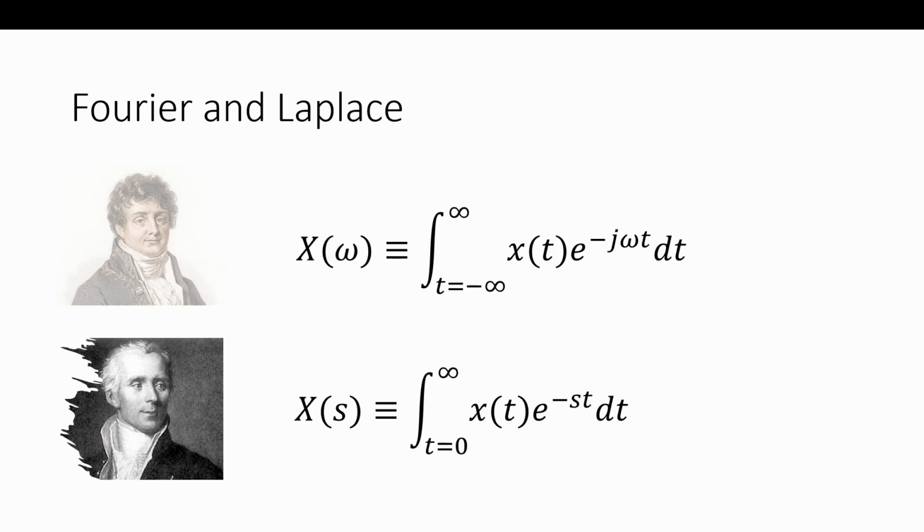And the process of doing that, if this x of t is exactly the complex conjugate of that, then it's spinning exactly the opposite way. It keeps landing on a real axis, and then we accumulate, and it grows to very big numbers. That's correlation. The noise in it will go down the longer we look, and the signal goes up. So we're correlating each frequency.